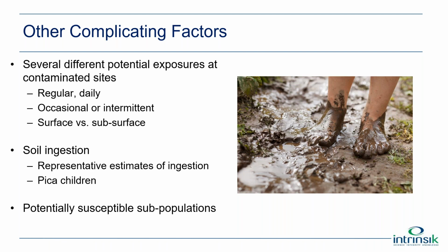It's important to have realistic exposure parameters, and for contaminated sites, a common one that comes into play is soil ingestion. Are the representative estimates that you're using for your assessment based on a longer term average exposure, or are they applicable to a short-term or acute exposure? Are they applicable to the type of person that you're looking at?